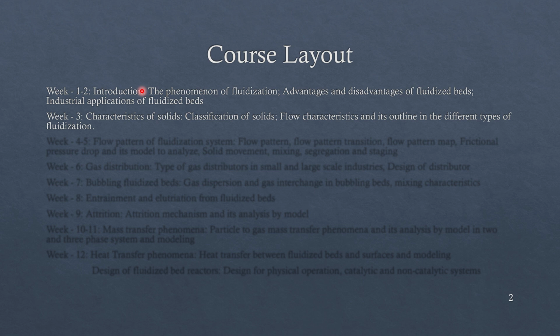These are very much used in industries because they do not have bubble formation at first, and they are easy to fluidize compared to Geldart C particles. As you all know, FCC catalyst, the fluid catalytic cracking catalyst, comes under Geldart A.